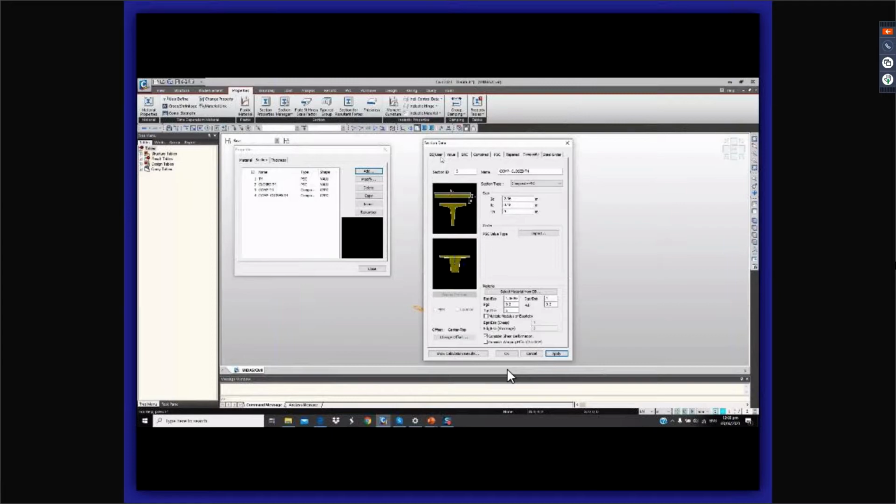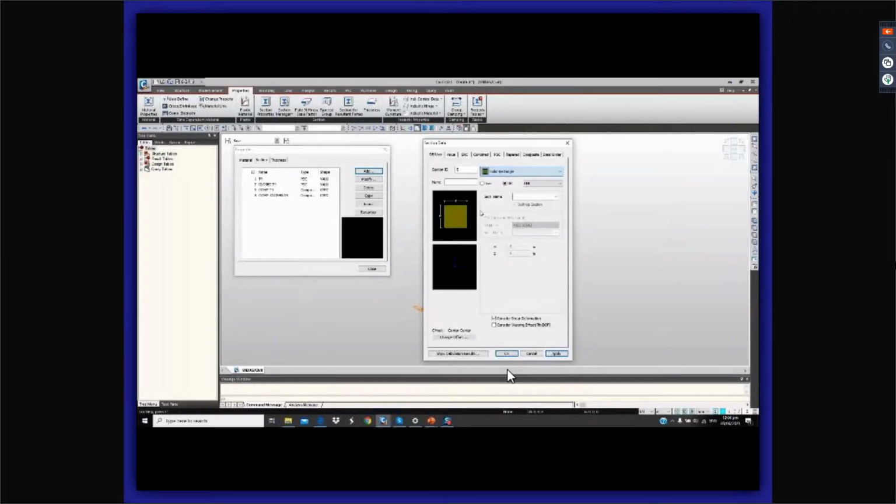Then the other section properties like the column, tier cap, and the diaphragm will be modified here in the data user tab. So first the column, let's define the column. So we need to have solid round and then the diameter of the column, click on apply. Then let's also define the tier cap or the coping beam. So coping beam is a rectangle, also in user defined. Let's change this to center top, click on OK.